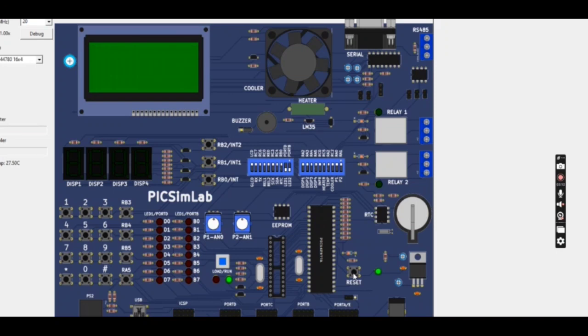When we power on the microwave oven, we can see the display powering on, and we have different modes: micro, grill, convection, and start. We have to select the mode which we want. So I am selecting micro now. It first displays 900 watts, which means in this mode we use 900 watts of power, and we have to set the time now.